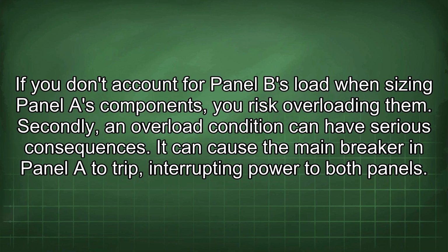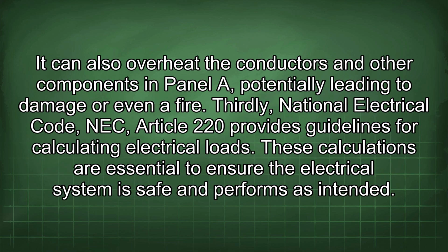Secondly, an overload condition can have serious consequences. It can cause the main breaker in panel A to trip, interrupting power to both panels. It can also overheat the conductors and other components in panel A, potentially leading to damage or even a fire.